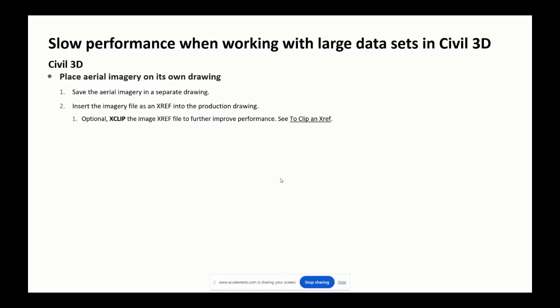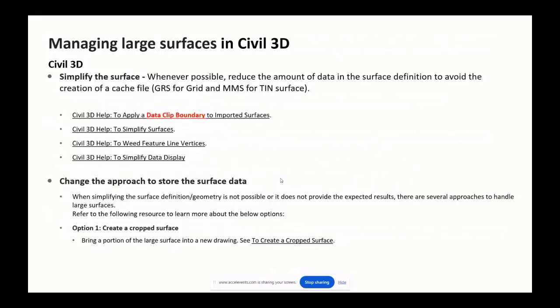There you go. Helpful. When you create that separate drawing, do you bring the image in? How do you attach the image to that drawing you create just for the image? I do map insert. Okay. Map insert. I didn't know if there's a different way to do that. No. I would still do the map insert. And that puts it into the drawing? Does it save it, or is it referencing it still? Puts it into the drawing. Okay. And then you reference that drawing into your file. Sometimes I have issues where I still send that file to someone and the aerial's not with it, even after map insert. So that's because it's an XREF and it won't. Okay. So you'd have to send that image with it.